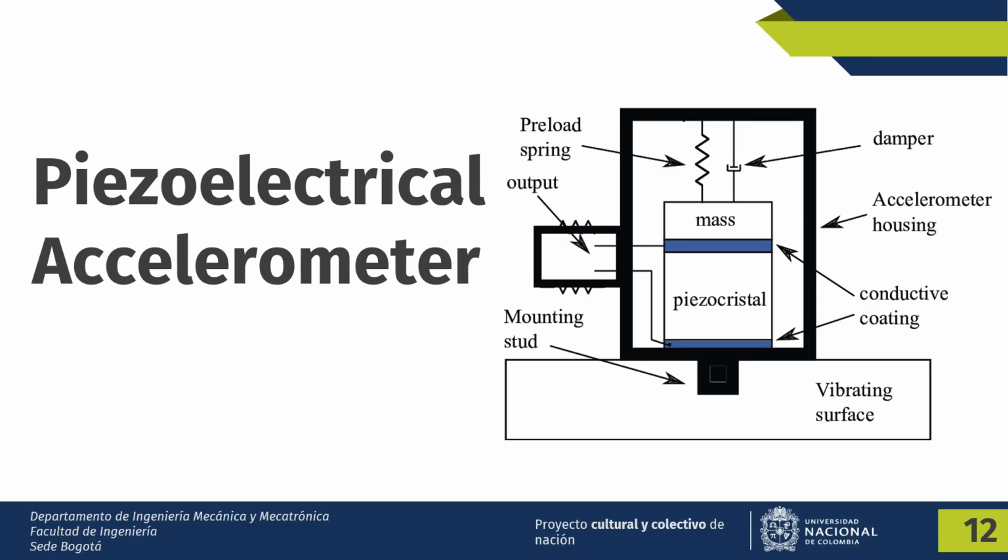Piezoelectric accelerometers contain a piezo crystal such as quartz or PZT that generates an electrical current when under strain. The deformation of the crystal due to acceleration provokes a voltage which is proportional to the applied acceleration. These sensors are well known and used for being highly sensitive with a fast response, ideal for applications with high frequencies like vibration testing.